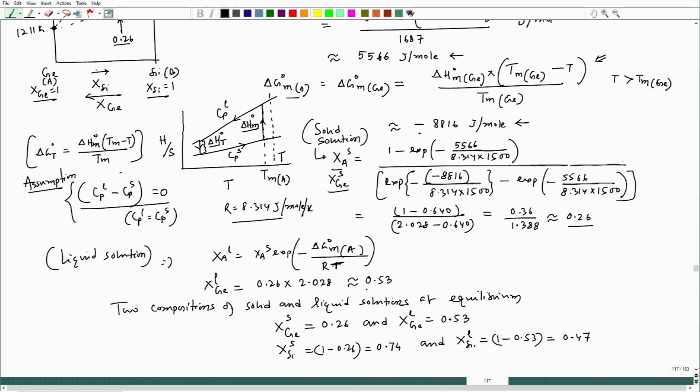That particular phase diagram is completely based on ideal solution consideration, that means Raoultian behavior of solution, and the values may not perfectly match the practically determined phase diagram, because Raoultian ideality is very difficult to achieve. So there will always be some enthalpy contribution, in terms of the bond energies.